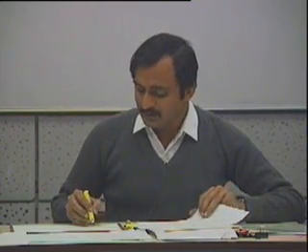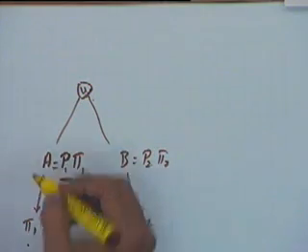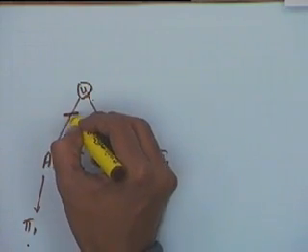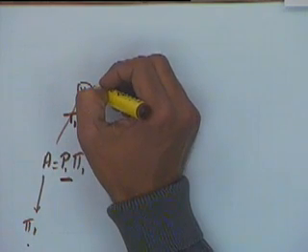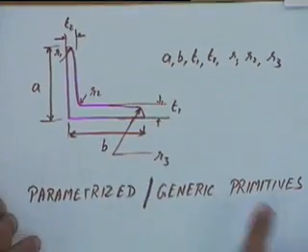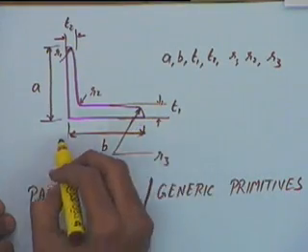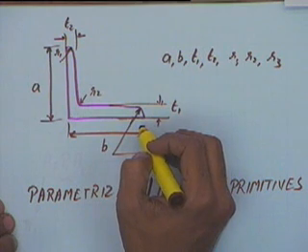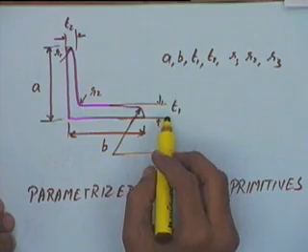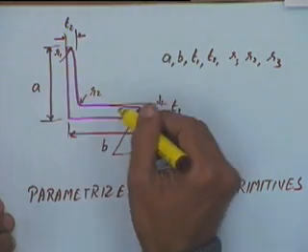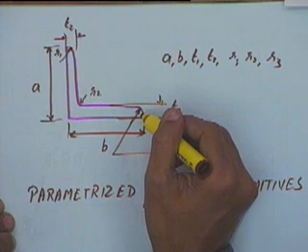Okay, so typically if you are talking of a CSG model using parametric primitives, in that case we will have a process of parameterization, then again of course there can be a transformation also. This parameterized primitive can be transformed and then used in a Boolean operation, because just a single transformation cannot help us to get the different sizes of the angles. But if I give it a non-uniform scaling in a two direction, the different parameters will not change proportionally.